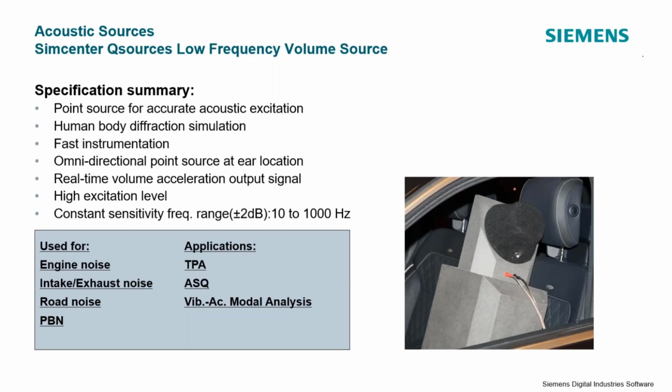Very, very neat. So then if you imagine in your TPA setup, it's not unlikely to have 50 acceleration locations. You're measuring all 3 directions of all 50 locations all at once with a single measurement. So it's very, very fast, way faster than trying to go around to each of those locations and hit with an impact hammer. Not to mention all the repeatability problems you have with an impact hammer.